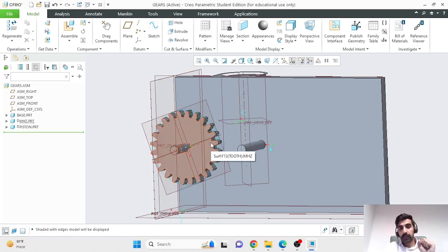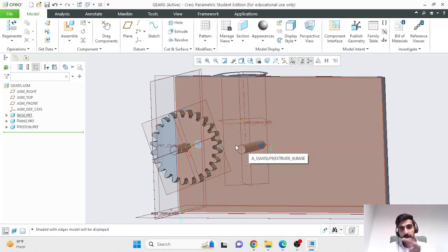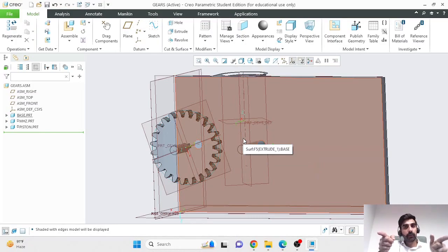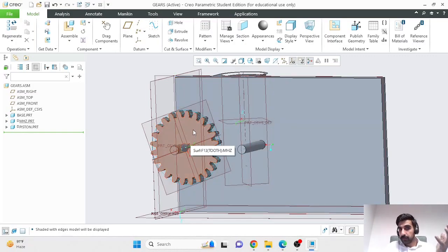What we'll do now is add a gear, an identical gear in this case, on the second shaft. I've placed the second shaft at a distance equal to the pitch diameter of these gears, so that the pitch diameters of the two gears would be tangent. Then we'll apply rules of mechanics, whereby when we move the driver gear, the driven gear would move corresponding to the gear ratio, and the speed and torque would be transmitted accordingly.